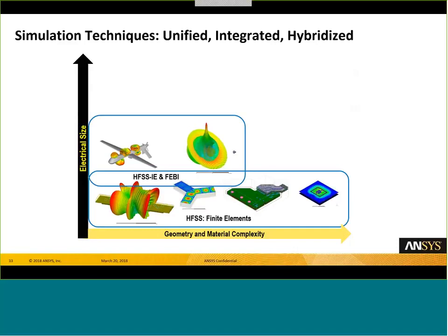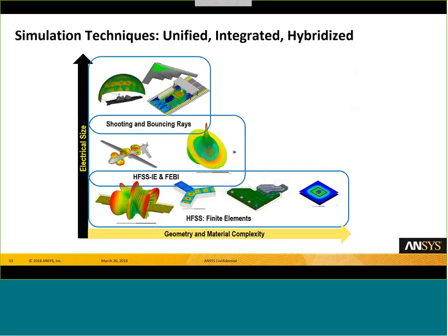Furthermore, you can link these two techniques in a single model, project, or interface so that the most efficient technique is actually leveraged. So we can continue this progression to include enormous objects that are hundreds or tens of thousands of wavelengths in size by switching to shooting and bouncing rays, and an even more dramatic speed up and hardware efficiency is actually realized.